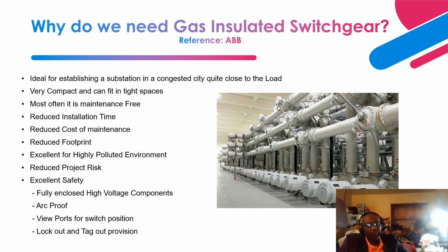If you have a congested city with a high population, and it is quite close to the load, then that is when you have to think about a gas insulated switchgear because of the enormous attributes that it has.